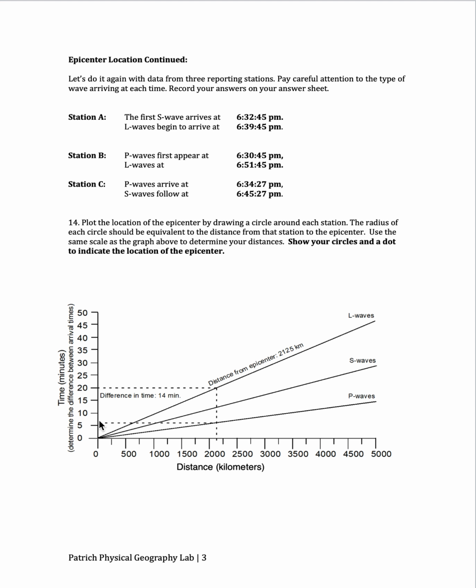So you take that piece of paper and with that perpendicular line that you've drawn, you move downward until both top and bottom of that line fits perfectly within it. Then you draw a line going all the way down. Then you're done with this part here. Now we're only going to deal with this part down here. New piece of paper, you measure from 0 to the point that you intersected here, and that is your physical distance in kilometers of which the earthquake happened from you.